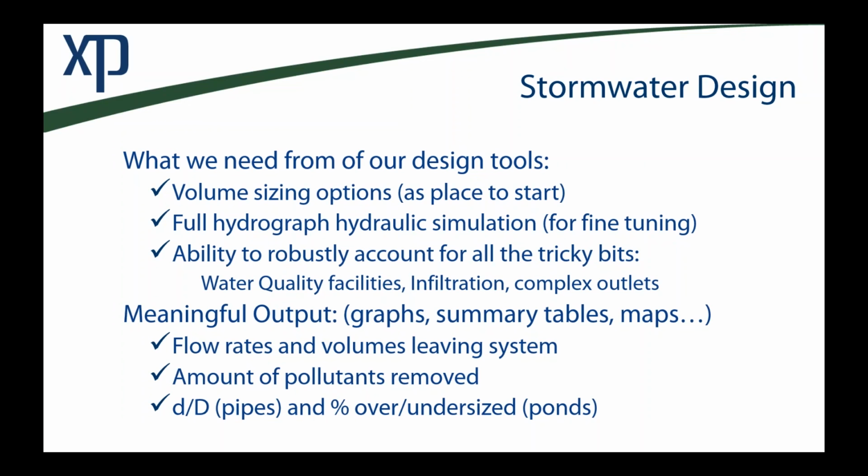Similarly with ponds or stormwater controls, I want to see if my system behaves correctly, right? So if I'm attenuating enough. But one real key indicator would be how much over or under capacity are my ponds or green facilities. So seeing just a percentage of I am 15% oversized or 15% extra volume, well, we only want the smallest size that we can get away with to be safe. We don't want to waste space. So that's something we could easily scale our facilities up or down if we have that kind of information.